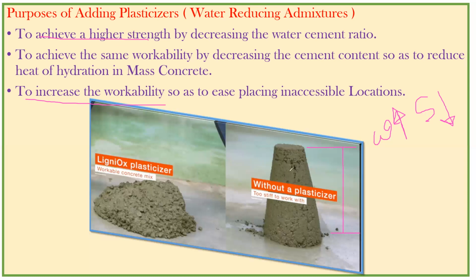Now imagine you're placing a concrete like this in the foundation. I'll draw a foundation here. What will happen? The concrete will remain in this way only. Again, you have to deploy a person, you have to use a vibrator, only then your concrete will be flowable.